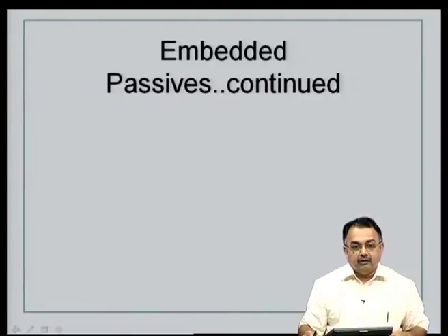Ultimately, the fruit of these exercises is to get a system level printed wiring board that is highly miniaturized, that has very high density in terms of components. At the same time, we are also looking at how best the electrical performance and thermal management issues are being taken care of when we employ embedded passives.